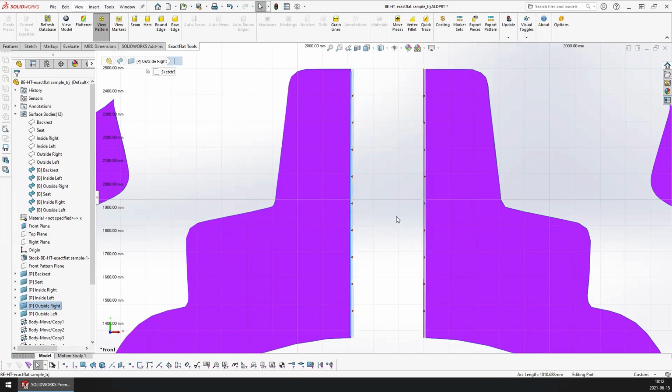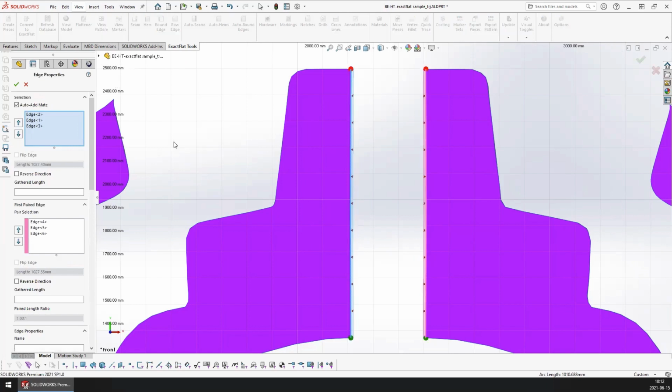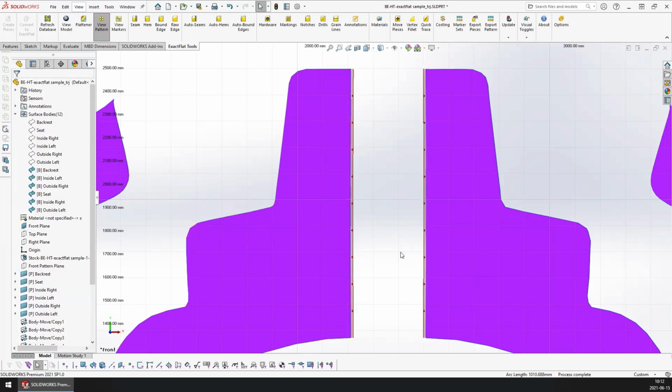In most cases, after you've finished modifying or creating a new seam, your edges will still be selected, and the implications here are if we go to open up the seam PMP again, if you already have an edge selected when you open up the seam PMP, your seam PMP will be opened up in edit mode. So you will be editing the seam that you just created. If you notice that you already have a seam there, just go ahead and click the red X. That will close the PMP. And then click in the white space to deselect your edge. This will deselect the edge and allow you to create a new seam.